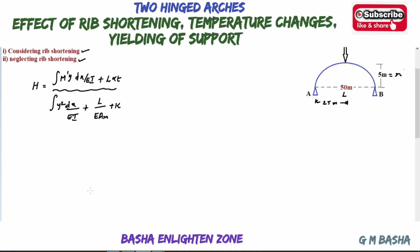First go for the numerator part, that is integral of M dash y dx by EI. Solve up to this part and then substitute the L alpha T values, which are given directly in the question, where L equals the span, alpha equals 12 into 10 to the power of minus 6, and T equals 20 degrees centigrade. First I will solve up to here, M dash y dx by EI. This is the same as previous problems. If the span range is 0 to 50, we consider 2 times 0 to 25, like the property I explained in the previous problems.